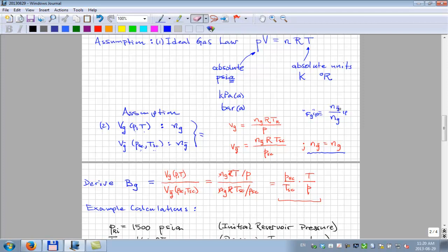It's because, okay, so if you can come up with this is FG, you'll have a new variable in the equation for BG that takes into account for the fact that how much of the original gas becomes surface gas depends on how much liquid it condenses out, and how much liquid it condenses out depends on what the reservoir pressure and temperature are.